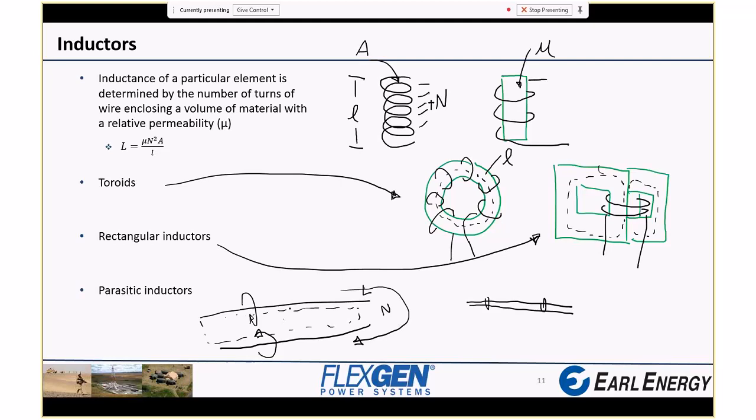So if you do this with your signal cable and you put a power cable running right next to them, now the magnetic field of the power cable, which may be pretty high intensity or high frequency, is coupling right into your signal cables and then can be generating noise. So a lot of reasons to keep both your power and signal routing tight.